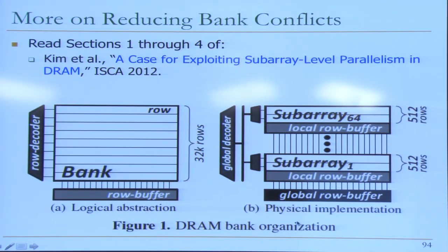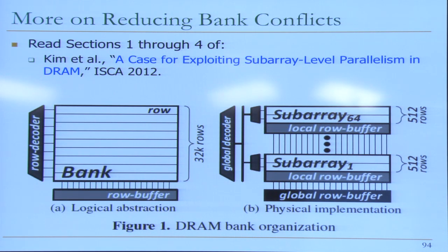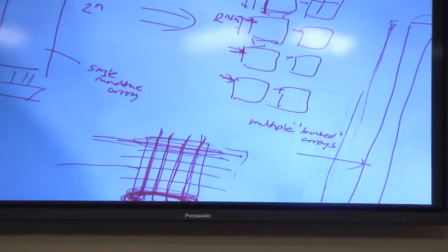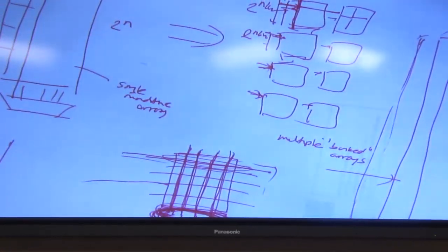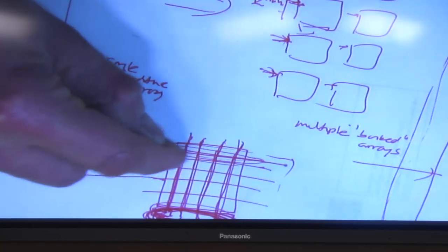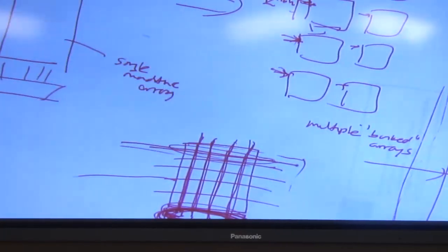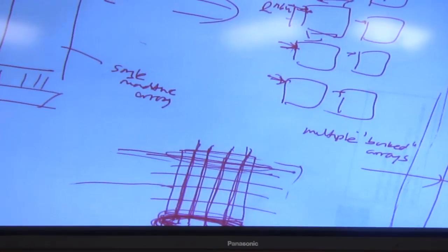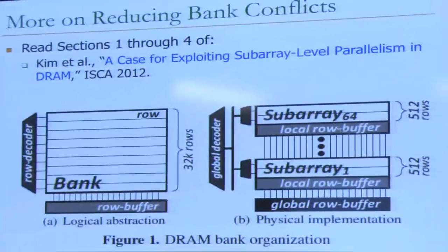That's a lot easier, because now you actually have a lot more drive capability if you go back to these sense amplifiers over here. Because these sense amplifiers can drive the global bit lines much better, because they actually are cross-coupled inverters that are big. They're much more powerful than the simple capacitor that we have over here. That's why it's designed this way. So what I told you is the right abstraction, because these subarrays are actually not exposed to the memory controller.